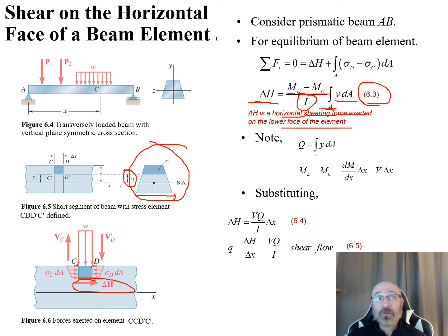So now what we want to do, now that we have our free body diagram and we defined what H is, let's take a look at our summation of forces and do our equilibrium analysis for our X direction. So what forces are acting in our X direction? Well, summation of force in the X direction, we can come back down to our diagram and look at this, and we can say, well, I see three different forces that are acting in my X direction.